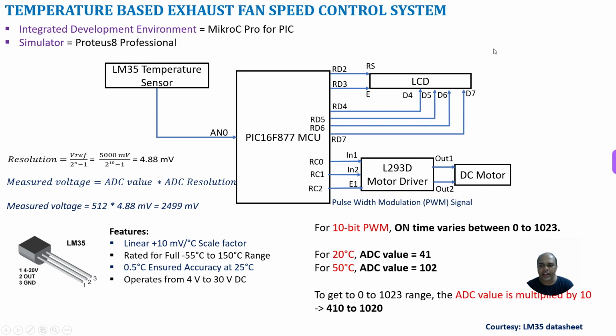And we are going to connect a 16x2 LCD in 4-bit mode to your microcontroller, where D4, D5, D6, D7 from your microcontroller pins are connected to D4 to D7 of your LCD pins. Same way RD2 is connected to register select pin of LCD, RD3 is connected to enable pin of your LCD.